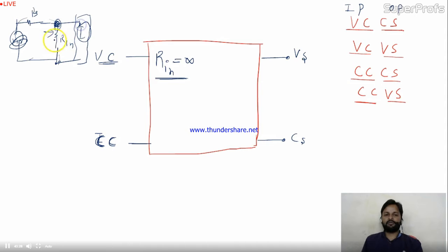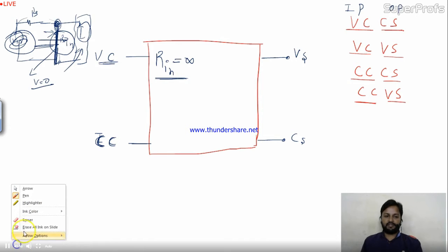What you want to do is give your amplifying circuit the full input. If you want to give the full input, you need to take this Rin as infinity. If Rin is infinity, the entire voltage will come over here. If Rin is 0, what will happen? The voltage is 0. What will you amplify now? Nothing. Is it okay? So similarly, I'll write for these 4 terms also.